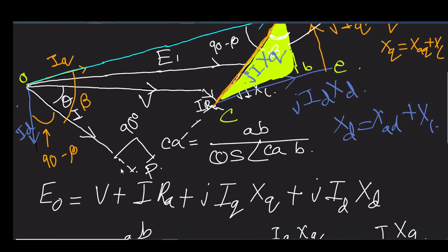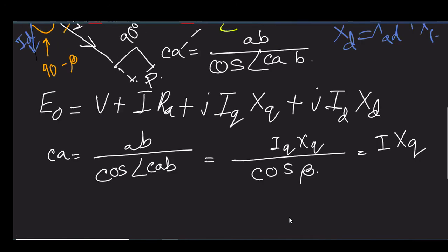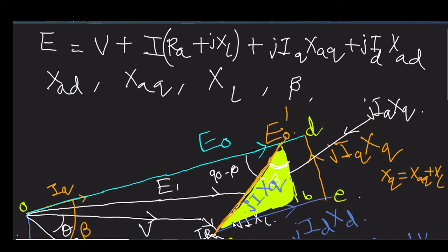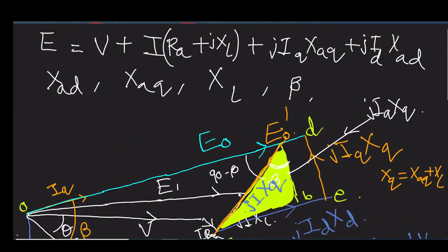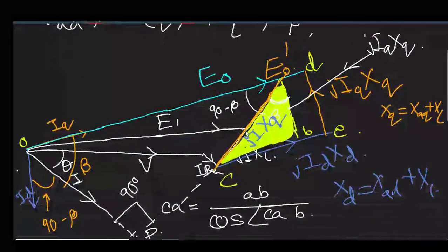So what I was discussing is that this is for the unsaturated case. Obviously for saturation we cannot even think of a phasor diagram, because saturation leads to nonlinearity. But still, as I said earlier, a piecewise linear type nonlinear system can also be treated like a linear system for piecewise analysis. So here it is the case.